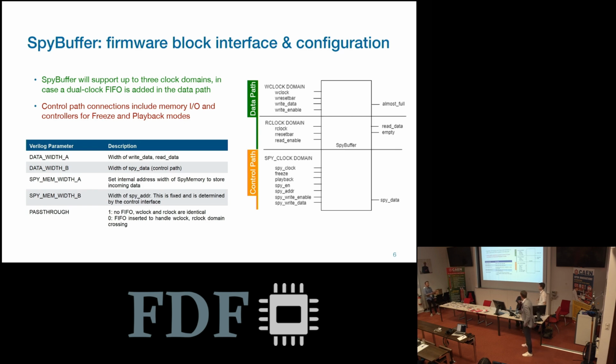When you copy that Vivado template that you say is described, that one will generate block RAM if it's described in a certain way, or it will generate UltraRAM. So maybe what you could do is add a switch that switches between the two implementations, and then put there a parameter that says block RAM or UltraRAM, and then switch between the two descriptions. It's true that by the way you describe it, Vivado will choose which of the two to use, in all cases, you mean? Yeah. Okay.